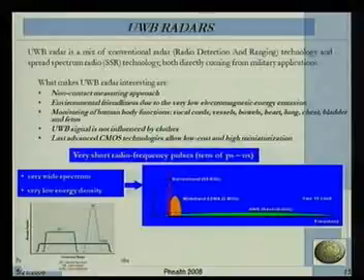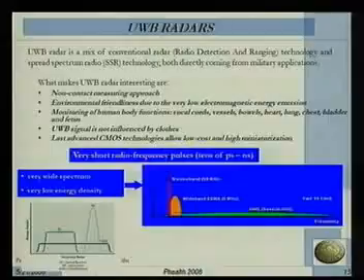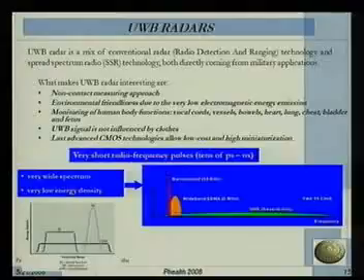The ultra-wideband radar mechanism is very similar to ultrasounds because the monitoring strategy is the same. It is based on the pulse echo technique. We have a pulse generated, and by processing the backscattered echo, we can estimate the position and the nature of the target.